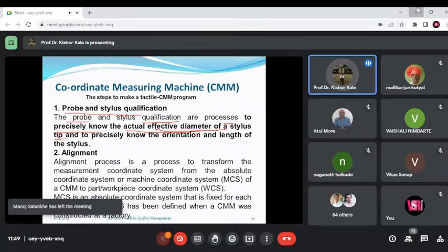That means if you get thousands of points as cloud data, each point belongs to which surface, that is traceable. We can find out its traceability. That means these thousand points are also collected by the same, and it knows from where each is being collected. That is the important aspect of the coordinate measuring machine.